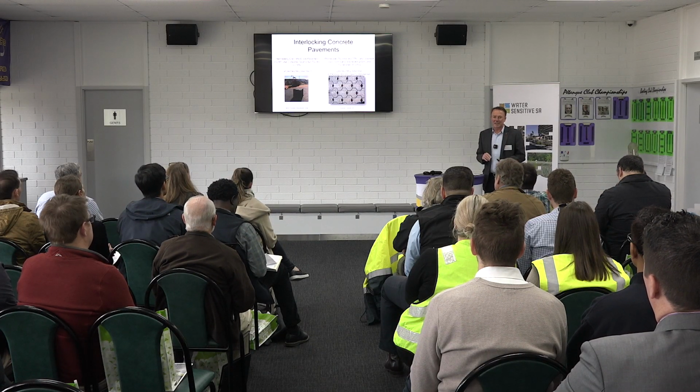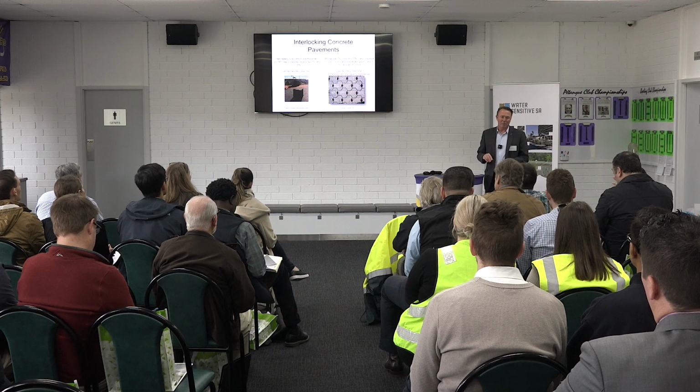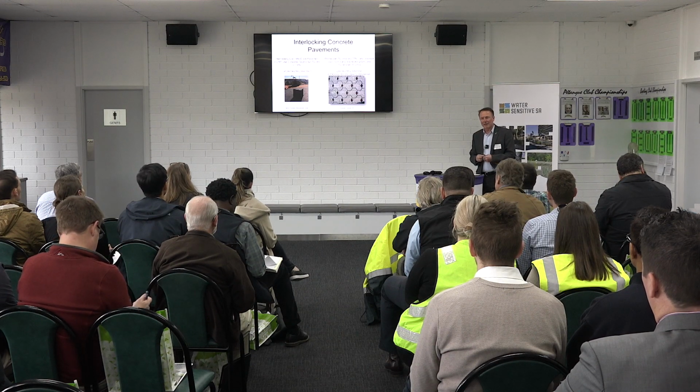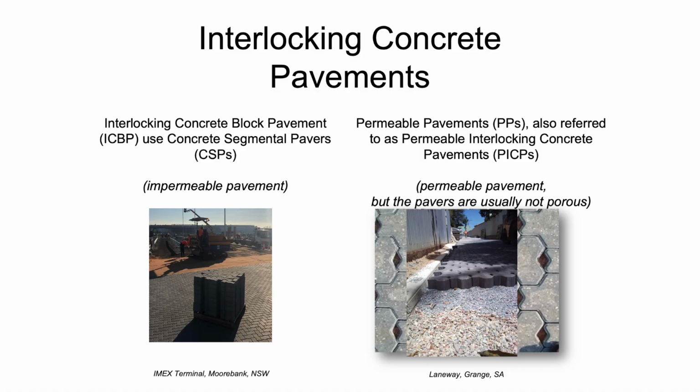The terminology is terrible in Australia and incredibly complex, but I want to pick up one of the points Arlene made, and that is we're not always trying to pave the world. Quite often in these systems you'll have some hard standing areas that are not permeable or not even pavers, perhaps asphalt, and then you might have an area that you want to drain onto your permeable pavers that might be interlocking concrete pavers, but they're not permeable. And then you might just end up with your most downstream part as being permeable pavers.